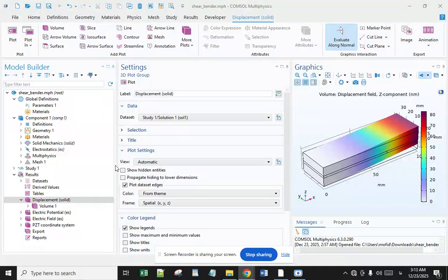The variation of the beam's tip deflection with the actuator's thickness was also evaluated. It can be seen here that the shear actuation mechanism is more performant than the extension one for thicker actuators, as can be expected. Therefore, for the case presented, the extension actuation mechanism is more efficient in a low range of T, larger than 2 mm, whereas, as noticed from this simulation, for T equal to 2 mm the shear actuation mechanism tends to be more efficient than the extension one.